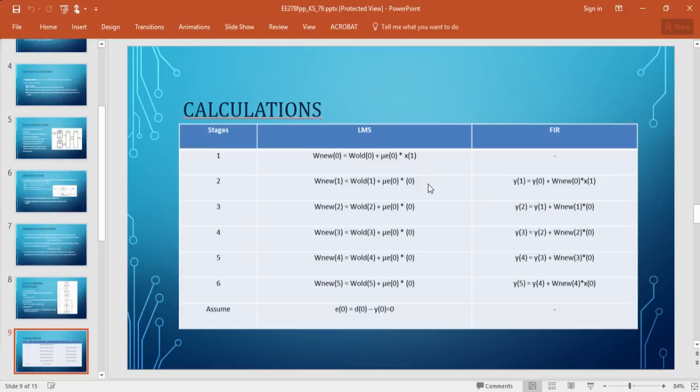The operations of the LMS algorithm and the filtering take place along with the delayed inputs, along with the multiplications of the coefficients which are generated by the LMS algorithm. It gives the signals which are added according to the taps. Say for example, for the 4-tap filter, 4 inputs are multiplied along with the coefficients to give the output, and all the 4 outputs are added to give the valid output.